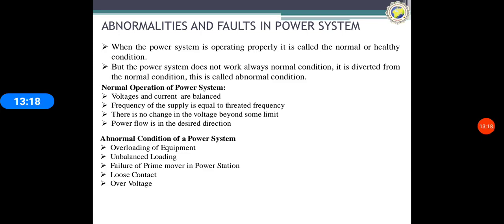When the load on the generator is reduced suddenly, its speed increases and more EMF is generated, which may damage the insulation of the armature winding. The excitation should be decreased immediately to prevent this.